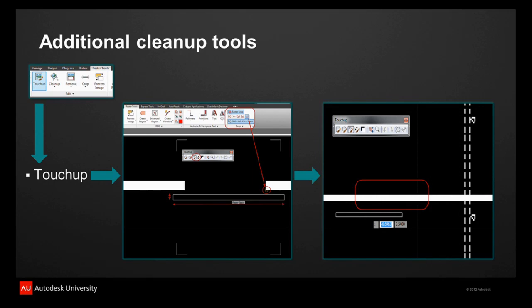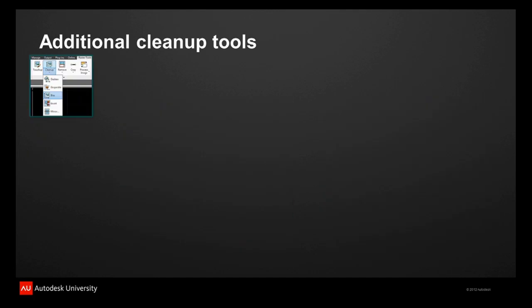And that is what the end result looks like. Right, so that's what I zoomed into a specific area where a continuous raster line was actually broken, and after the touch-up, that is what it looks like. So quite simple. This also saves this back into the image. All right, so whatever you are doing here is directly manipulating and changing the raster image that you originally inserted into your drawing. Another one I want to talk about is the bias tool.